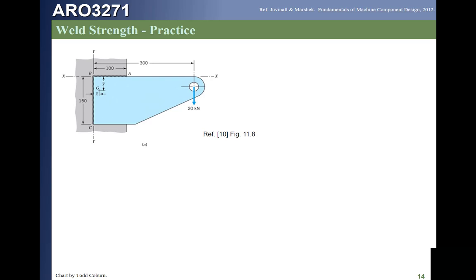Last time we looked at this, we saw this problem, and you guys told me that this was a 2D weld loaded in plane, and that's true. We can use the method from last time where we put in the properties of each weld and calculate the properties of the weld pattern. But if you look at this, you also notice that this L weld applies to the simplified procedure, and we can use the simplified procedure for in-plane loaded welds for this problem.